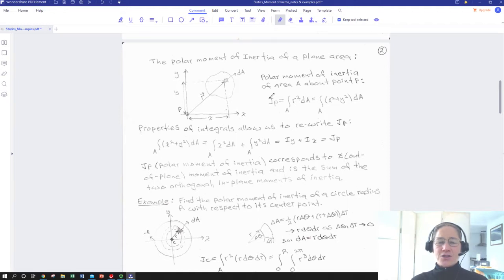So this J sub p is a convention that's typically used for the polar moment of inertia. You can think about that as maybe the moment of inertia around the z-axis in a polar coordinate system, like a cylindrical symmetric system. In this case, the cylinder's cross-section would be here in the page, and we're looking at rotating things around the axis of a cylinder coming out of the screen.